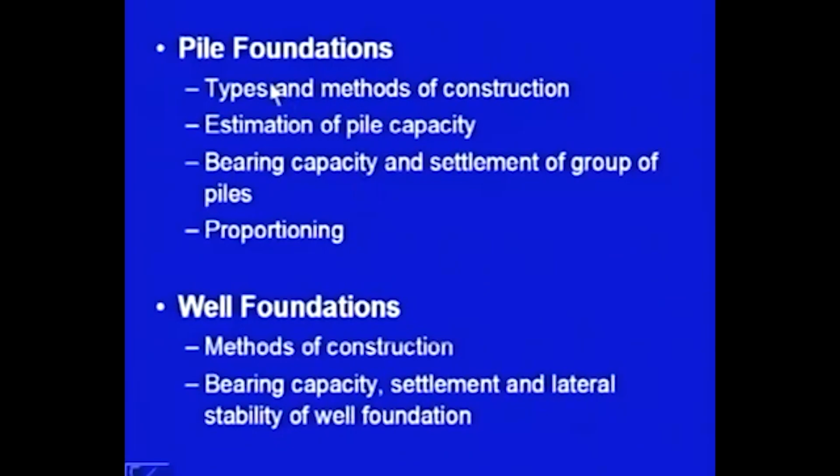After the shallow foundations, we will move on to pile foundations. Pile foundations are the foundations which are given when the load carrying capacity of the subsoil strata is not that good, and we have to transfer the load deeper into the ground. So, shallow foundations are not sufficient, we have to give piles, they are a little bit costly, and the loads can be transferred deeper where the strong strata, the competent stratum, is available.